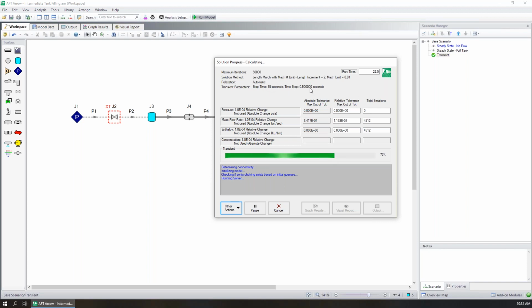Here we can see that flow rate relaxation is being lowered for every time step, I should say, rather. Again, that's one of the caveats that I mentioned. If you have a very complex system and you're trying to push that into transient analysis, because all it's doing is running a steady state simulation of your model over and over, it can run into those same challenges over and over. So that's why it's good to make sure that your steady state model is running well and running effectively, instead of just jumping directly into a transient analysis where the runtime is going to be significantly more. So our steady state runs, each of those were maybe 5 seconds at most. And now that we're running 30 of them, obviously your runtime is going to be more significant.